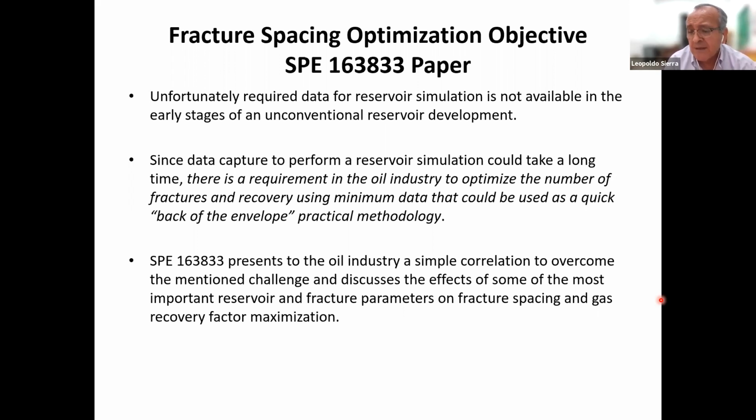I'm talking here about just knowing the reservoir permeability and the fluid properties, for gas or liquid, in this case oil. We are going to be able to develop a simple correlation to calculate the optimum fracture spacing. And I'm going to show you this correlation later.